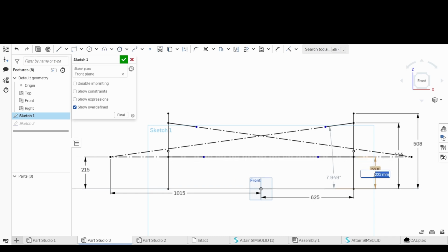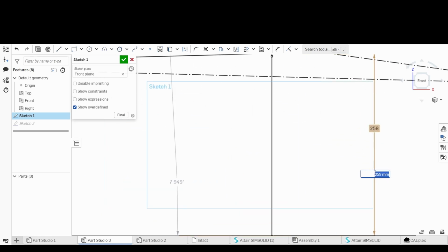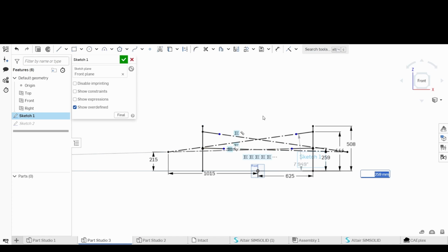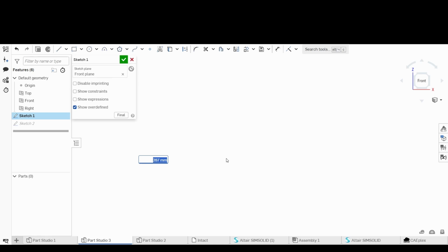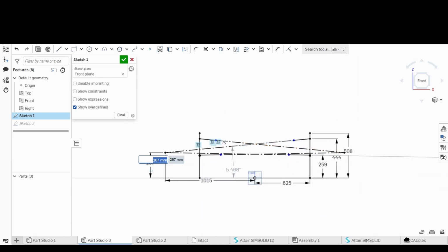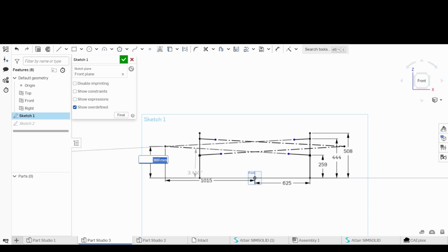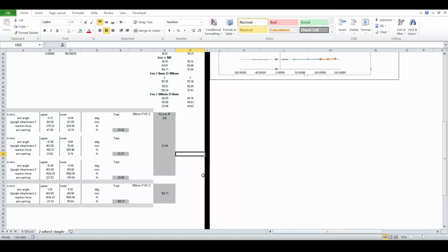I went to extremes to something like this. And I also changed the instant center location as well. To different points, and then did a few calculations of those different locations versus using the end line, and I'll show you the results of those. So what I did, I made different suspension designs, basically changing the point on the upright where it attaches, and also changed the instant center location once.